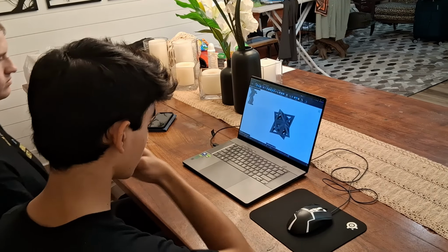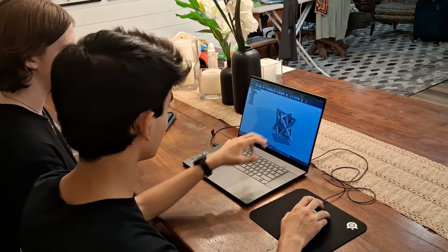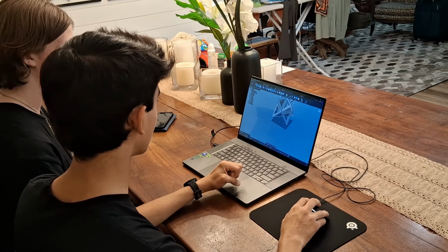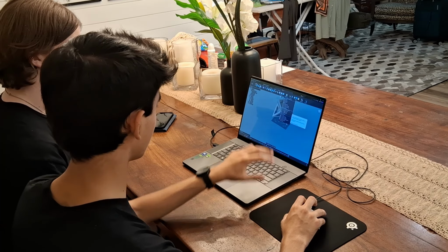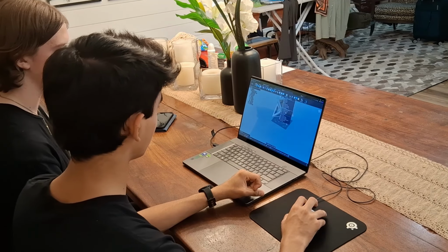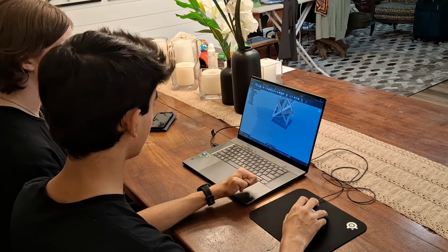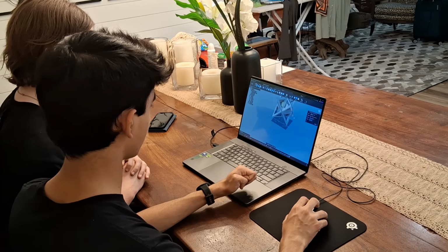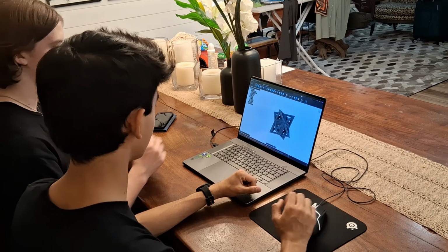All right. Nice job. So now what we're gonna do is we're gonna use this one little shape here and then duplicate it a bunch of times. All right. So what we have to do now is find our axis that we can make a pattern along. So we're gonna do an axis through these 2 corners here, and then another axis through these 2 corners here. All right, there we go. And just do those 2 axes.